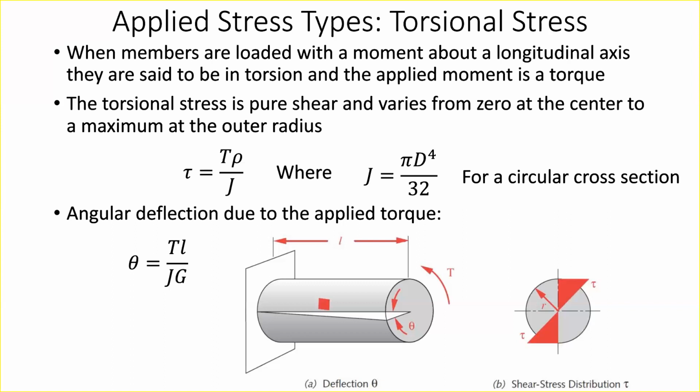In this case, it's what you would call the polar moment of inertia. So a little different than the previous case. In this case, we're integrating over angles as opposed to Cartesian coordinates to find that geometric property. But again, you typically just have tables that you can look up the equations for. So in this case, the rod is just pi, the diameter to the fourth over 32.